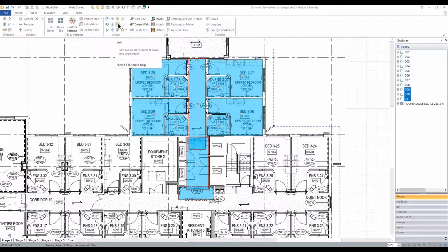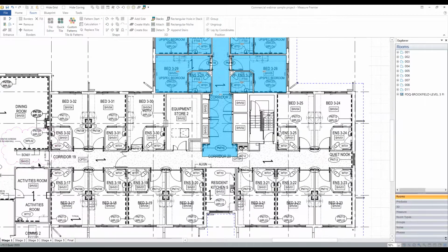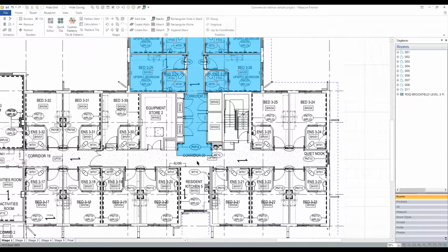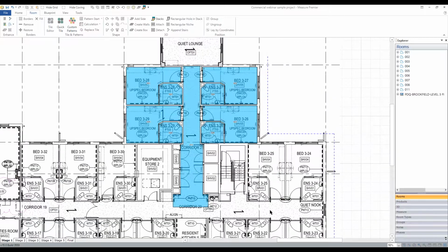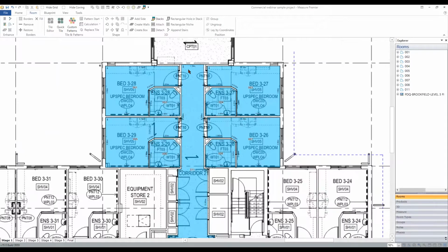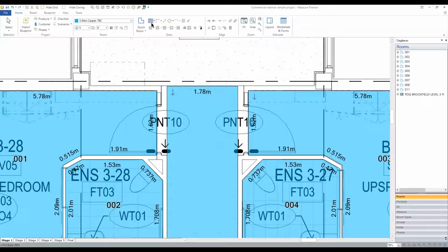So anyway, let's use that joining tool, and you'll see it's fused the corridor or those pieces into one. And that's quite useful, especially for a big long one like this one. You could draw it all as one rectangle and then go ahead and add these little bits where they jut in as rectangles, join it all together, and that would probably be quicker than going over it with line draw all the way around. We do have one other piece at the top here, so let's do that one as well. We'll do a rectangle to there and there.